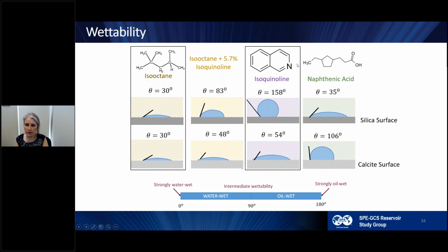So you may not understand why I'm calling these oil components. These are all petroleum products. They are processed in the refinery. After we produce the petroleum, we can get these components, so these components are inside the petroleum. And what we know as sandstone, we know that it is water wet. And for calcite, what we know, it's in general oil wet. But these examples are showing me that if my oil composition is changing, their wettability is changing as well.